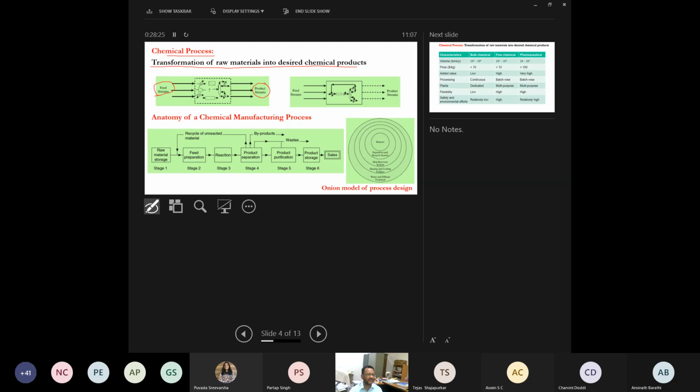First we have to identify the unit operations required to achieve the target from the source. Here you may have mixing, reaction, separation units. We need purification units, pumps, compressors, condensers, heat exchangers, reboilers, evaporators.